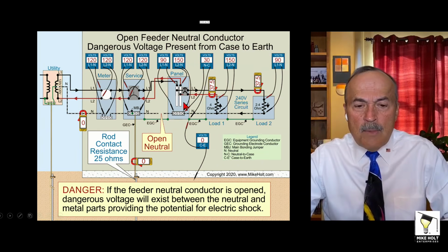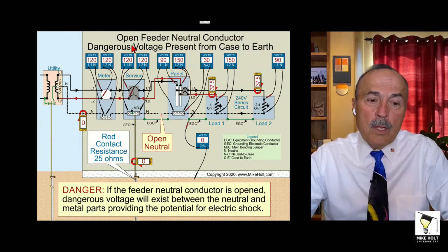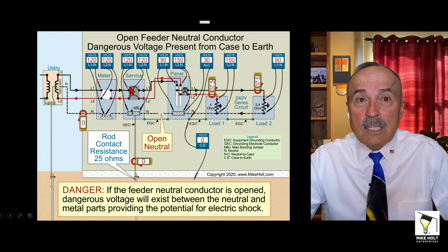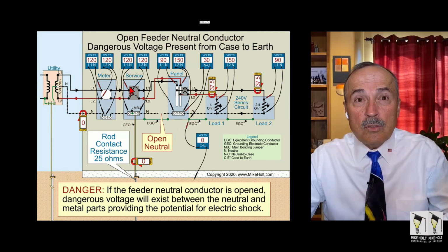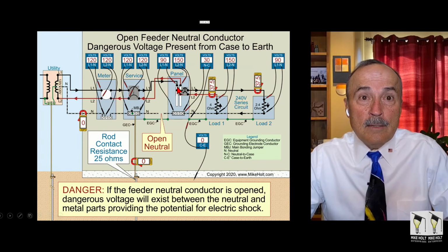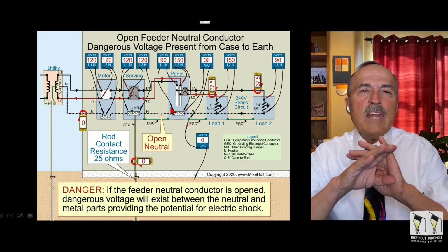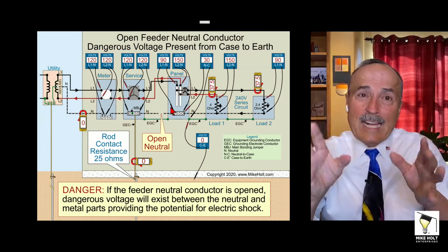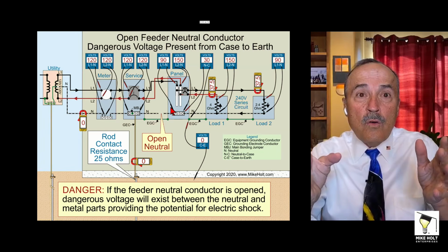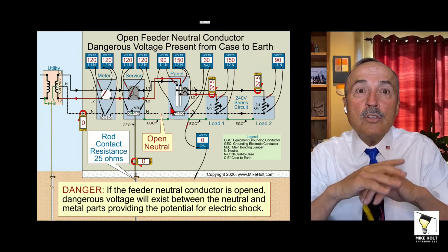So guess what? Somebody's saying somewhere, hey, the lights are acting kind of strange. You're like, okay, no problem. I go to the meter can 120, 120, utility, goodbye. I go to the disconnect 120, 120. That means from the neutral to the meter can and disconnect, we're good. I go to the panel 90, 150. Okay. That means between these 2 points here is an open neutral. You're going to look like a rock star. You're going to be like that within 5 minutes. You know that the feeder inside from the service disconnect to that panel, the neutral is open.